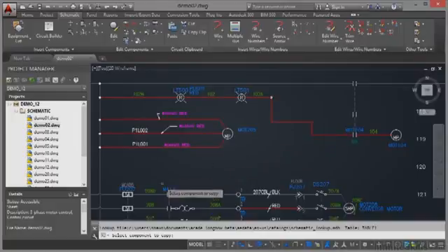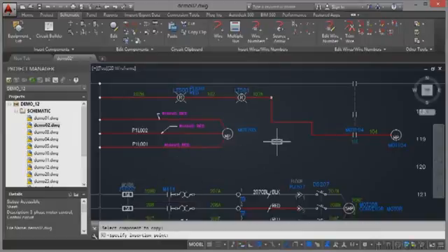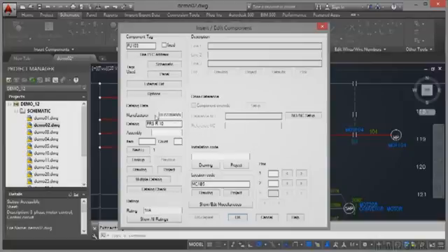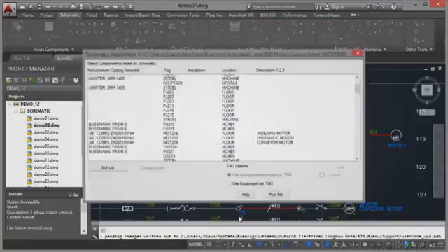You'll notice on the three-phase circuit below, there's some fuses here. Can you see that one there? It's a 5 amp FU207 tagged fuse. So I click there, there's my fuse. I click here, and it inserts that fuse. Picks up the catalog data straight away. FU103 is the next component tag. I click on OK now.